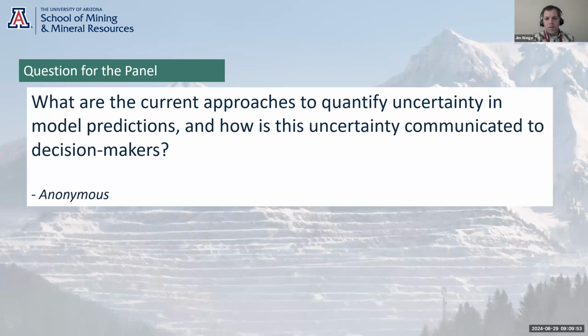One of the approaches that we use to get at the uncertainty is to run a series of sensitivities where we up the pressure to the phreatic surface by known units. For us, we'll run like 50 feet of additional head, up to 100 feet, and then 300 feet of additional head. And then we'll run those through the models to see how the geotech models behave with those additional head values.